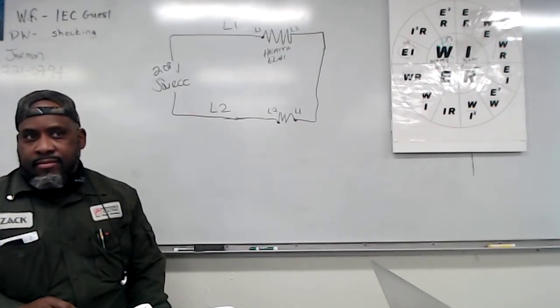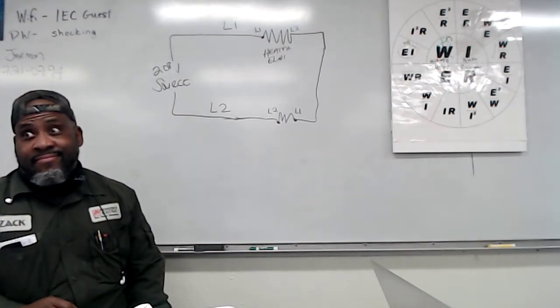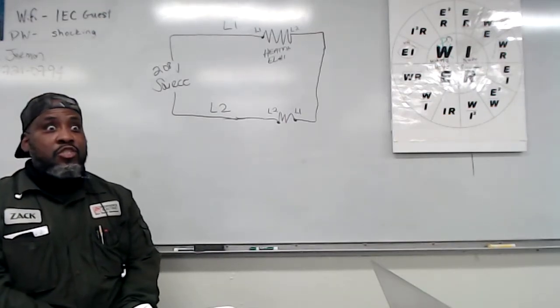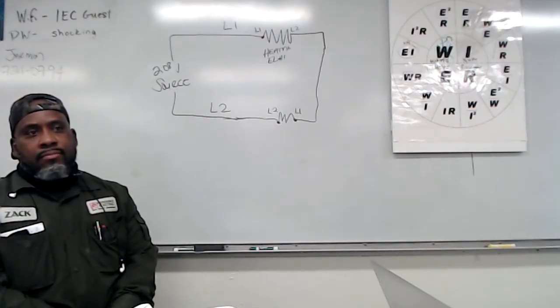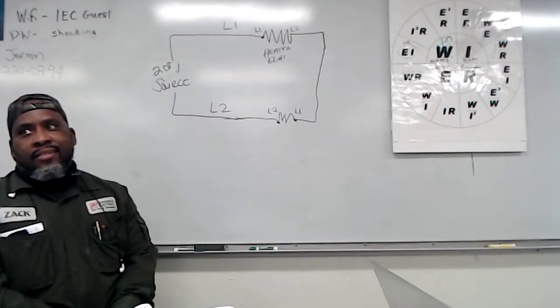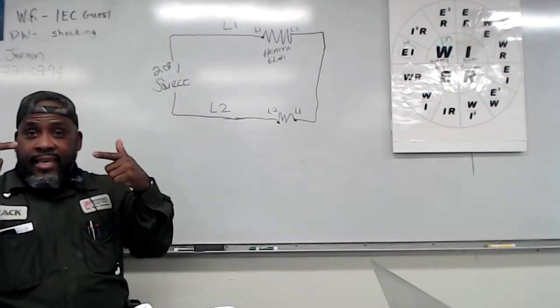So where's the return circuit? There is no return circuit. And you wouldn't have one in the element anyway, because you're just not a neutral. It's 220, no neutral. If you want to be technical, I had it explained to me like this: they're not hitting at the same time.